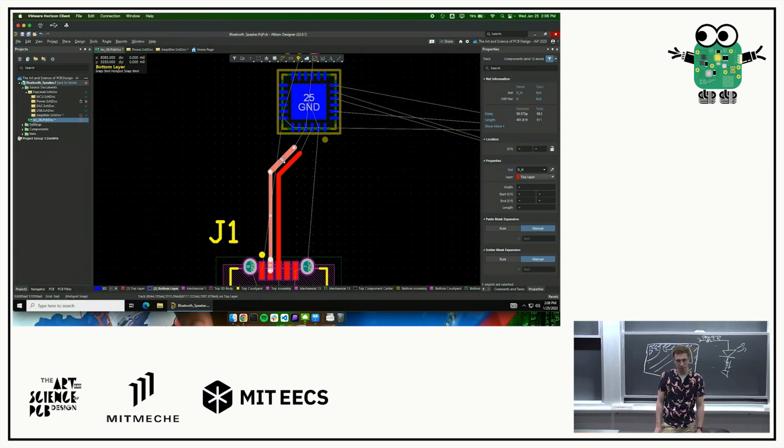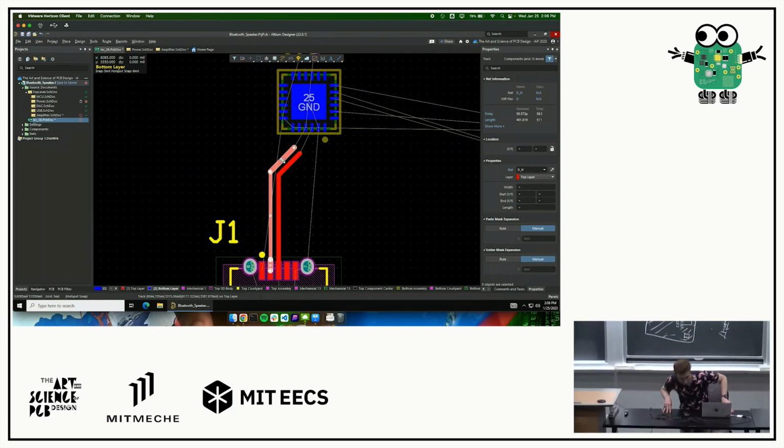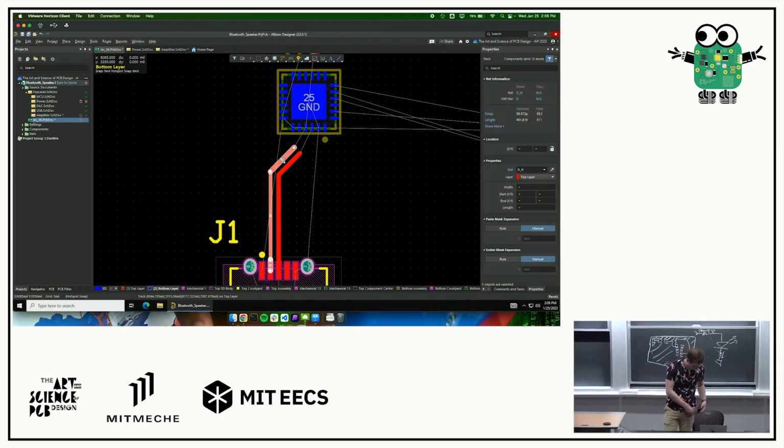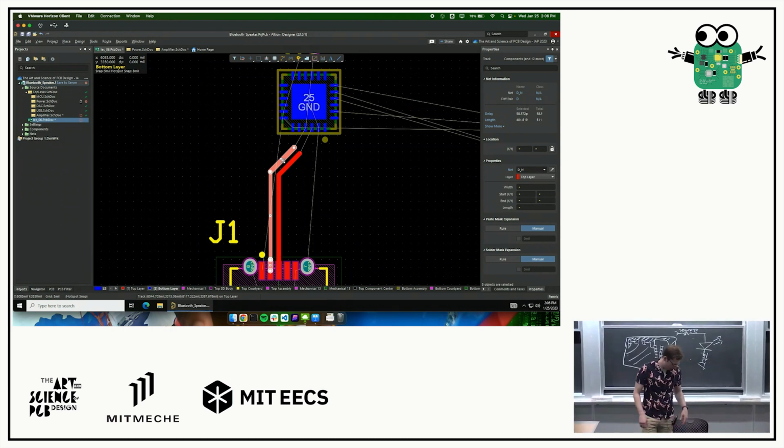And then also, like Fischer was saying, with the references, a lot of the time what will happen is when you have super precise analog sensing requirements, like if you're doing current sensing, because there are current sense boards that measure in the terms of nanoamps, or for very precise sensing applications, you want smooth, steady planes where your current is running through, because it minimizes, your cross-sectional area is massive at that point. So they'll use a thick plane and also a very wide plane to get that ground as smooth as it possibly can be.